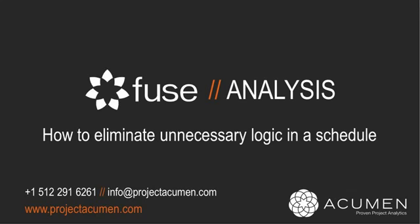Let's look at the impact and the benefit of eliminating unnecessary logic within a schedule. Very often when running a schedule critique, focus is given to identifying and resolving missing logic, or what we call open-ended logic. Well, in a similar manner, identifying and resolving, and more importantly, eliminating what we call redundant logic is equally important.